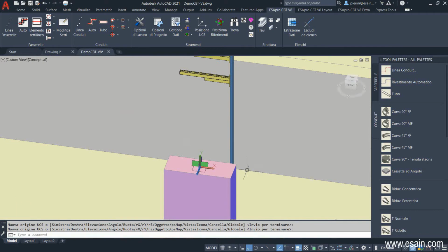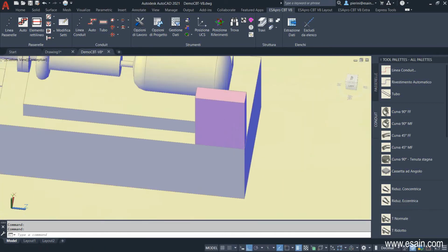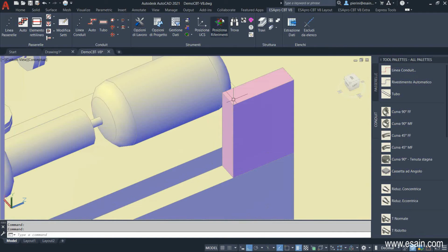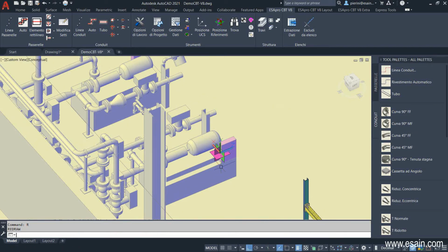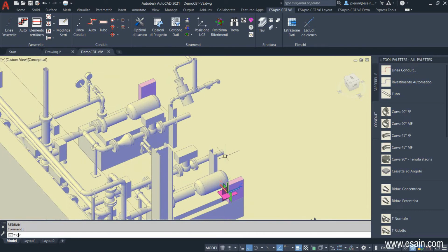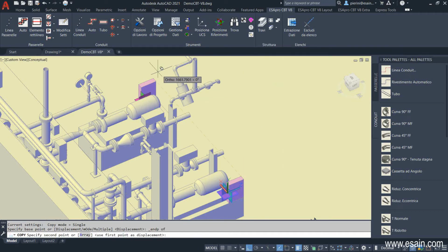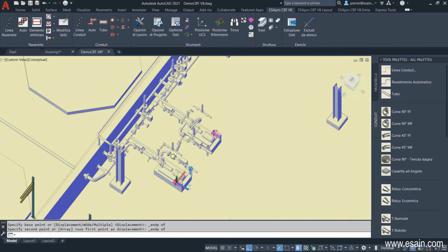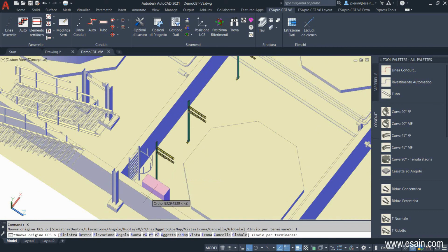Another above the pumps panel. And we're going to insert icons that are used to enter inside the terminal blocks. In this case, we set up a side entry. These symbols are actually AutoCAD standard blocks, so they can be copied with the normal copy command. One last reference about the terminal panel is missing and we're done.